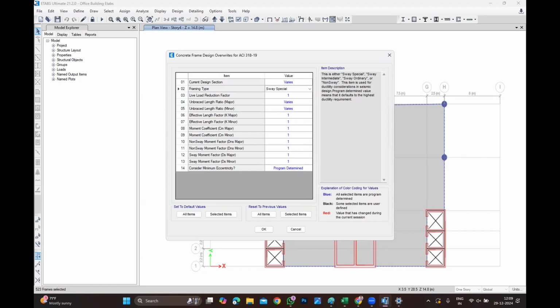Then you can check in the model whether he released or did not release. If something goes wrong on site, for example you haven't taken the column down, you can check the model. If he released it, then you can have a debate: I've checked the model and the column is released and considered free of movement, so why should I take it down? If site guys make mistakes, you don't need to remove all those things to repair it. You know how difficult it is, right?